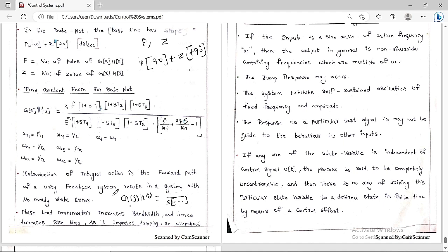the case of a transfer function, then basically we are going to increase the order of the system by 1 unit, as well as the type of the system by 1 unit. Whenever we add poles, the root locus is going to shift to the right half of the s-plane, so therefore the system can become unstable. Adding poles is something like a PI controller or simply a lag compensator.